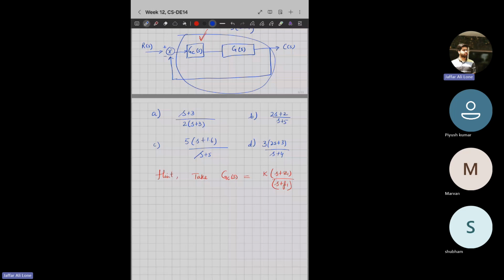It can be asked in general from your second chapter, second order systems, or when we learn closed loop systems, right? So basically you have to understand where this compensator is added. So it's always added in the forward path, right? So before the plant, because it has to manipulate it, it has to compensate it, right? So solve it and tell me what will be the characteristic equation.